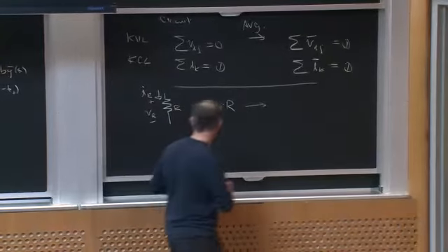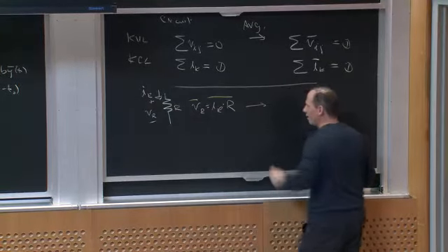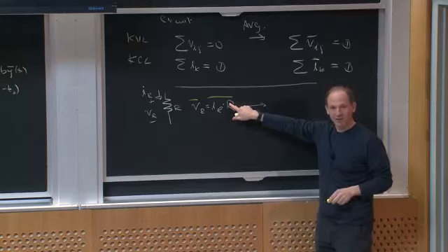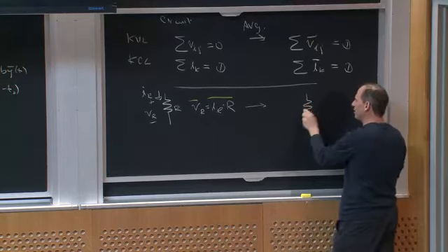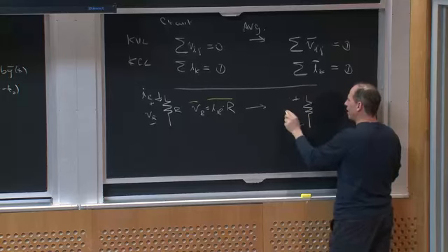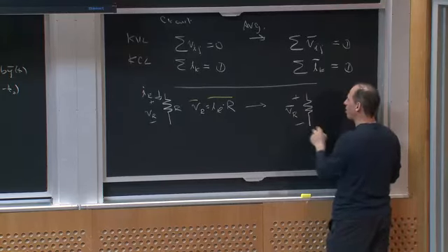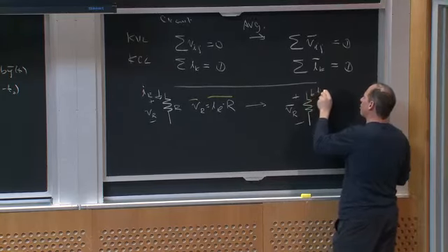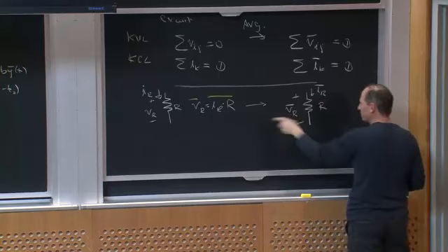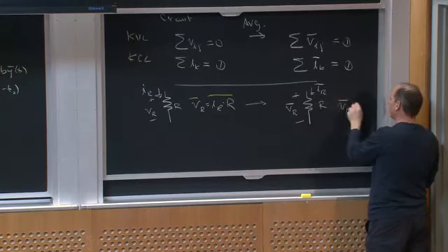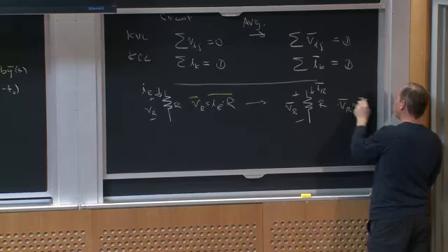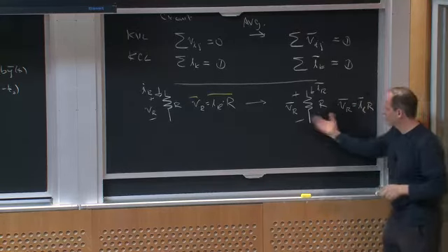So I'll average the left and I'll average the right, and I can pull r out of the equation, right? So then my averaged element ought to just be this, right? I have V sub r bar, I sub r bar, and r, and because my relationship is simply V sub r bar is equal to I sub r bar times r, which is exactly the relation of a resistor.